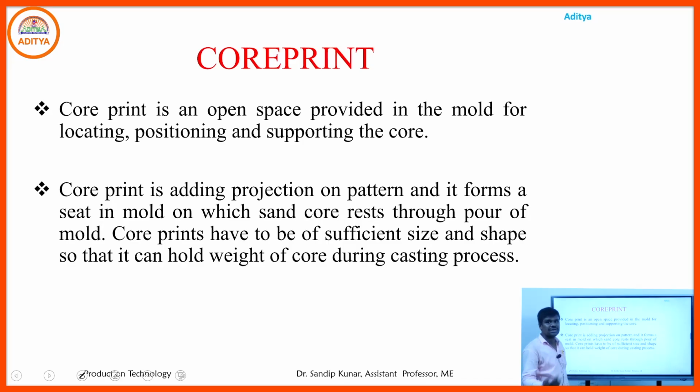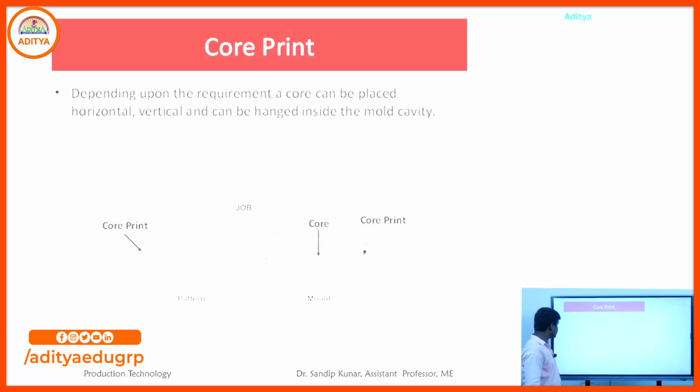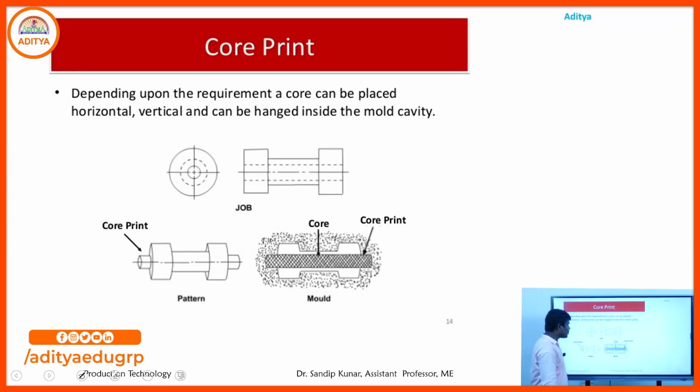Core print. Why do we use the core print? Core print is provided to the open spaces in the mold for locating, positioning and supporting the core. That is the main use of the core print.